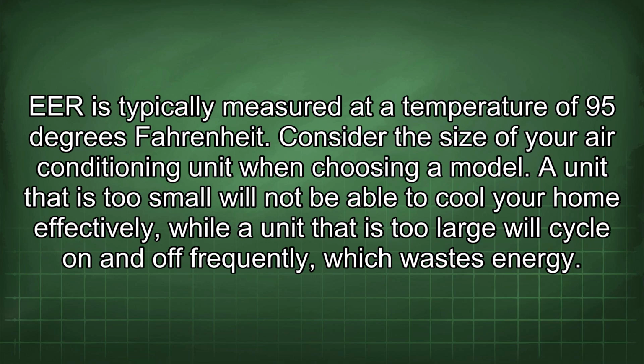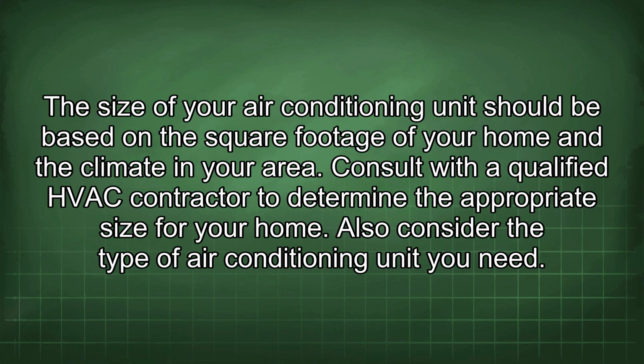Consider the size of your air conditioning unit when choosing a model. A unit that is too small will not be able to cool your home effectively, while a unit that is too large will cycle on and off frequently, which wastes energy. The size of your air conditioning unit should be based on the square footage of your home and the climate in your area. Consult with a qualified HVAC contractor to determine the appropriate size for your home.